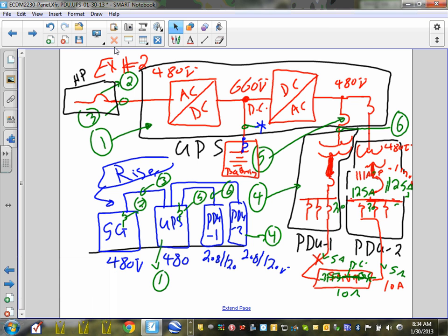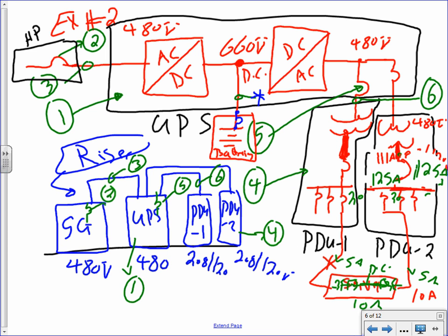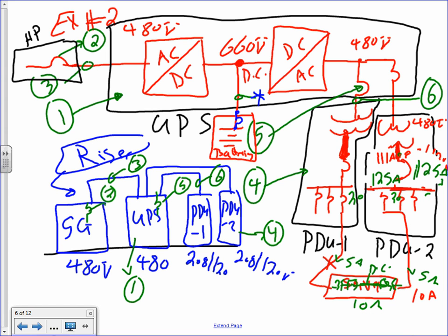Okay, my friend, if I can get you back, it seems you guys are almost done here. Okay, here's what I have for you. If you do me a favor, Aaron, my friend, this is a new topic, very important to you guys, which is UPS and PDUs. I take the stuff that we have in our project, by the way. This is directly from our project. So let me walk you through the layout. You guys have this picture. I have my switchgear, the 480. From the switchgear, I'm going to take a feeder and feed my UPS system. From my UPS system, I'm going to take a feeder and feed my 2 PDUs.